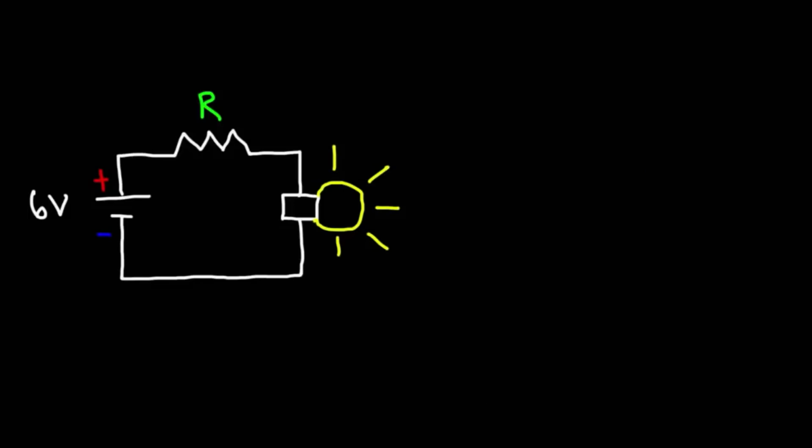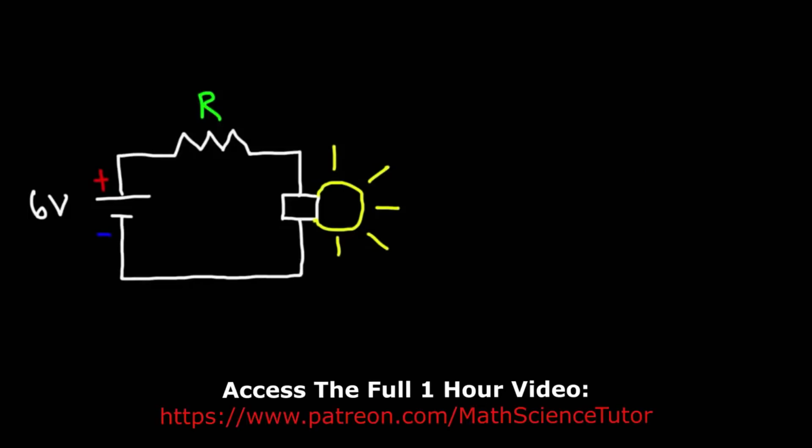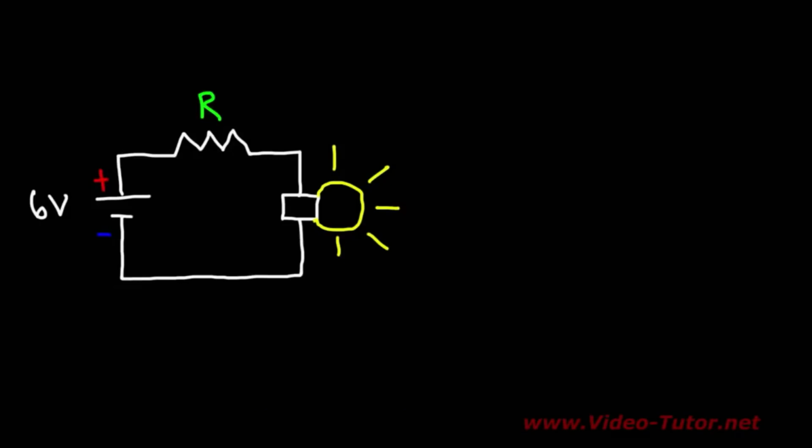Now the next type of device that we need to talk about is the light bulb. The light bulb converts electricity into light energy. And this particular light bulb does so through a process known as incandescence. In incandescence, when a metal gets very hot, it's going to become red hot first, and as it gets hotter, the color changes. It'll turn yellow, it may even be white hot. And so when a metal is very hot, it begins to emit not only heat energy, but light energy. And so incandescence is a process where you can generate light by heating up a material.